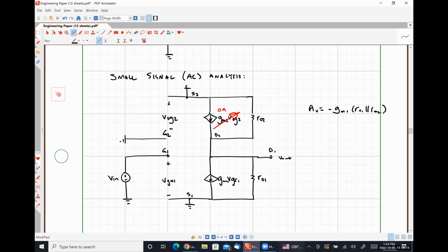A simple voltage divider circuit says it's going to behave this way to give us this exact thing, but as we take into effect temperature effects, as we take into effect power supply ripple and all that kind of stuff, we can't guarantee that we're getting exactly 10 milliamps out of this thing. And that's where we are going to have to start paying attention to how to do biasing that provides the rigidity that we really need to ensure our device operates correctly.